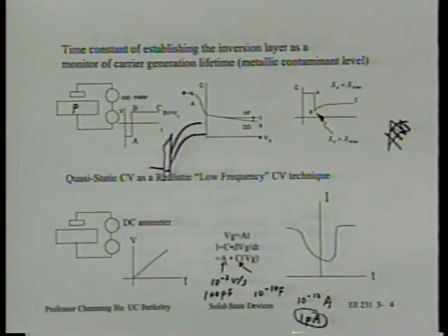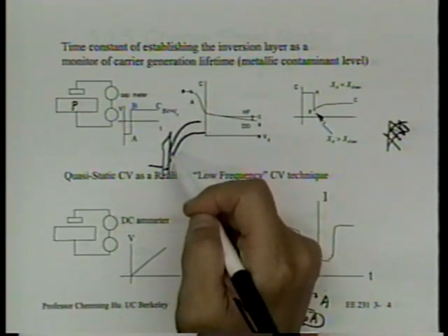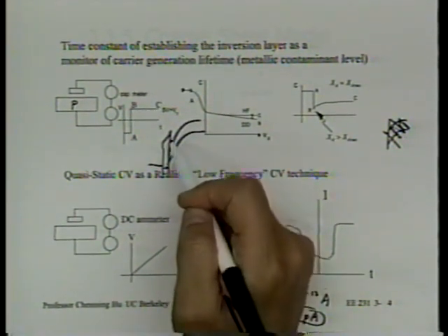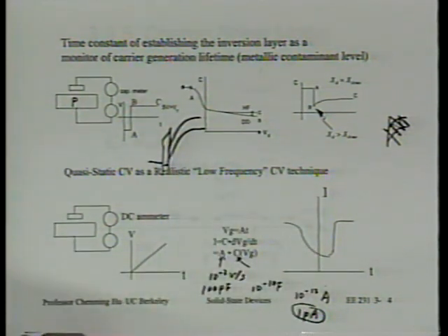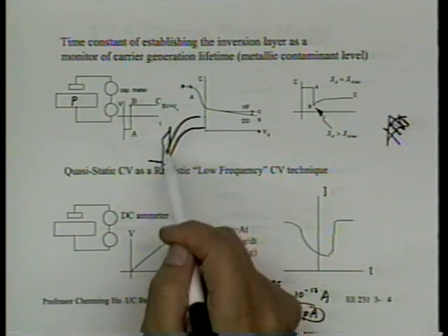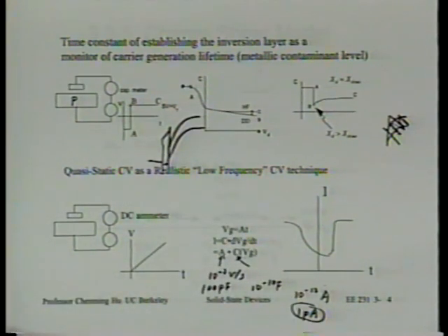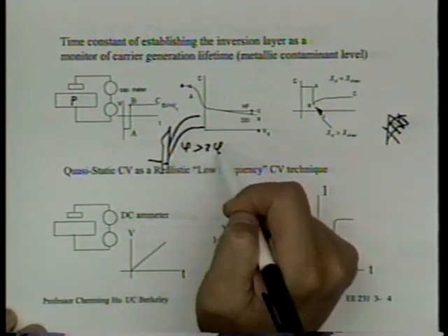Because once it exceeds 2φB, there will be so many electrons in the inversion layer that additional VG will show up in Vox, taken up by the oxide voltage, not by φS. Remember that? But at point B, there's no time for this inversion charge to be created. Therefore, band bending φS can easily exceed 2φB.